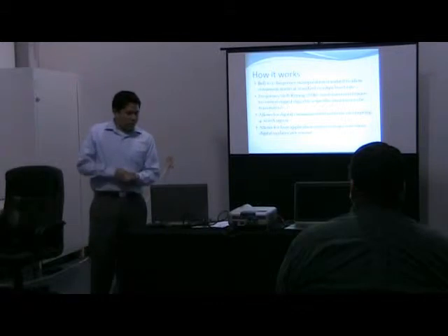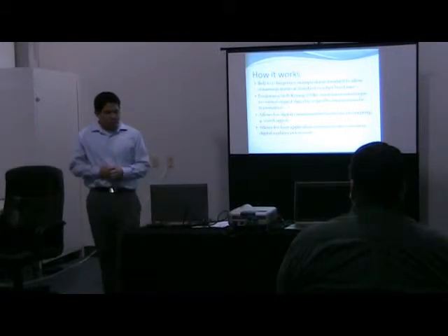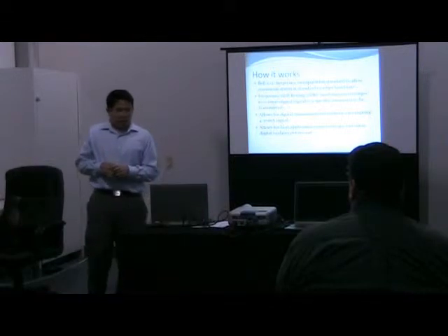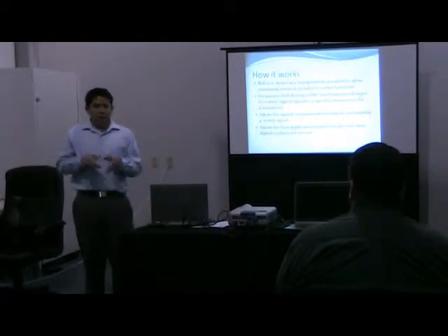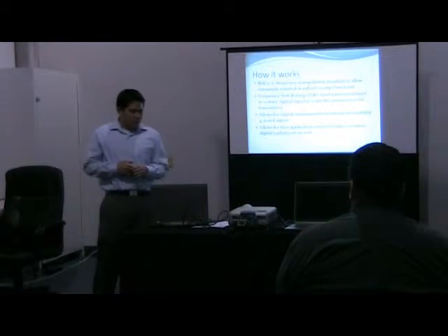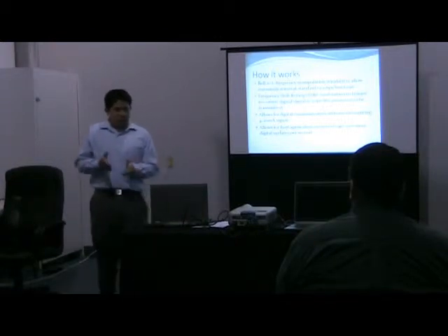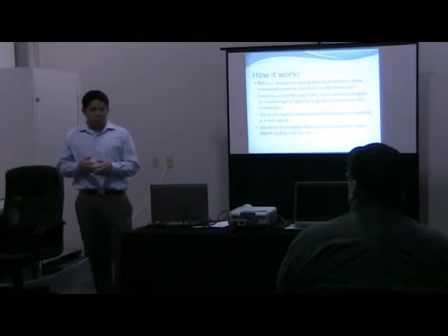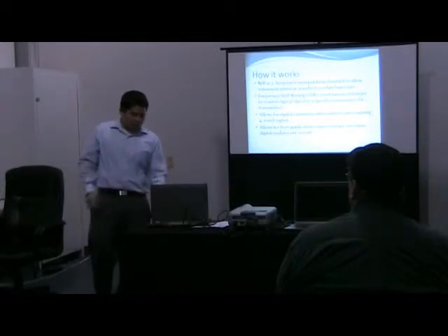So there's a little extra information on Bell 202 and frequency shift keying, but with these two technologies together, it allows for digital communication over the analog without interrupting the 4 to 20 milliamp signal. And at those speeds, the 1200 baud rate allows for a host application to get 2 or more digital updates per second.